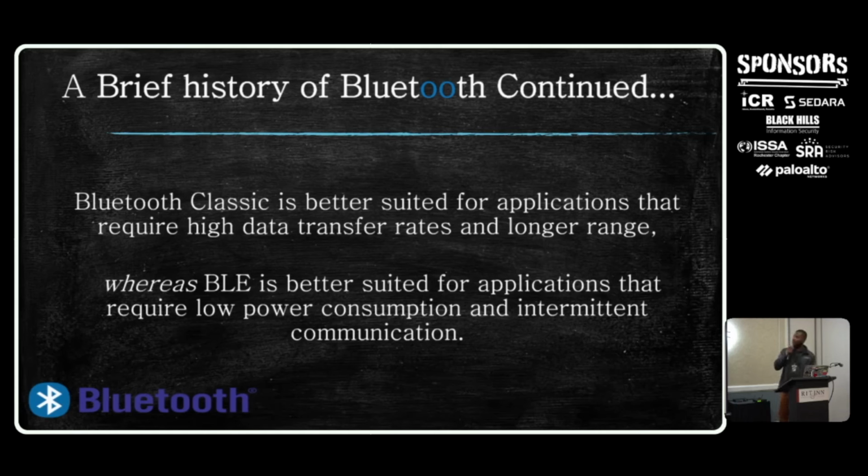So the Bluetooth specification, we're currently at version 5.3. One thing to keep note of is that what's often referred to as Bluetooth Smart starts at version 4.0. It's when security started to get a lot better. The majority of devices are still running 4.0, and we've had that spec since 2016. Even the device I'm going to show, the chip was compatible with 5.3, but the Bluetooth version was set for 4.0. So even newer chips are still using old protocols, and that's essentially part of the problem.